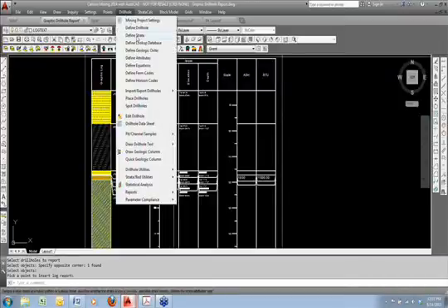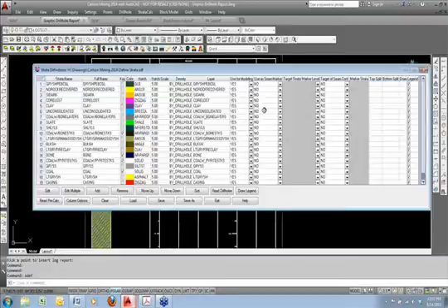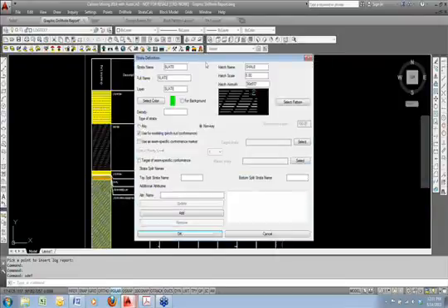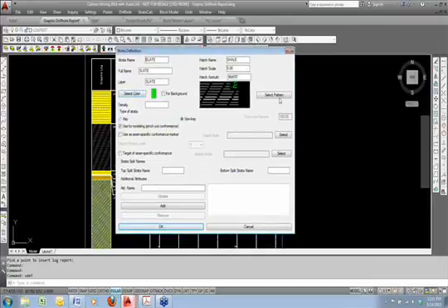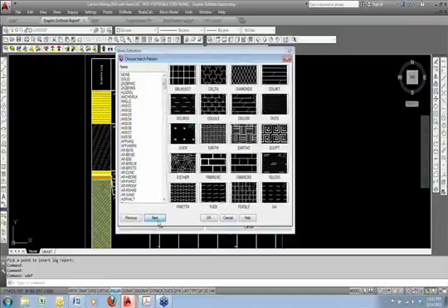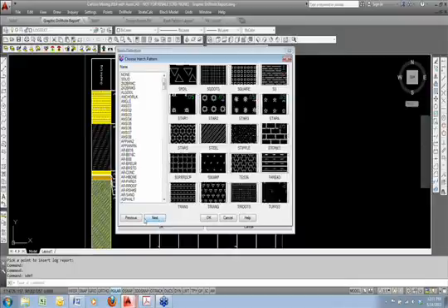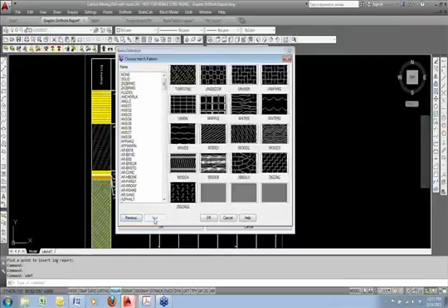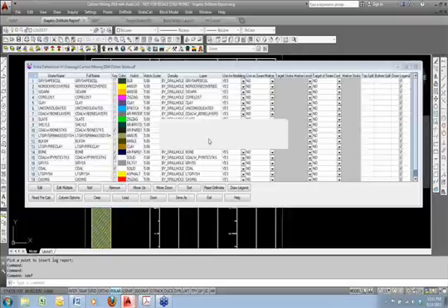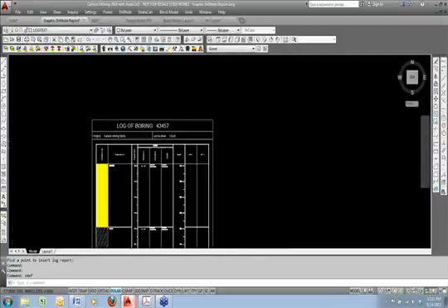The only thing that's missing to show is the define strata command, which is a prerequisite for that report. This just defines all the different colors. Let's find the slate, for example, and I'll edit that. That was set to be green. You can control your hatch pattern scale, and then you have several pages of geological hatch patterns that you can apply to the various strata. We've added some new ones in 2013, and they appear towards the end of this list. Okay, so that's the new graphic drill hole report.